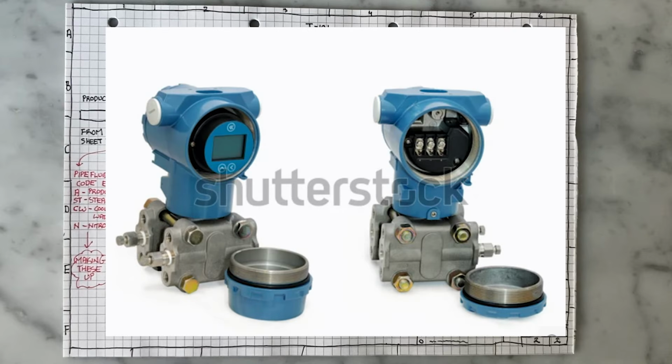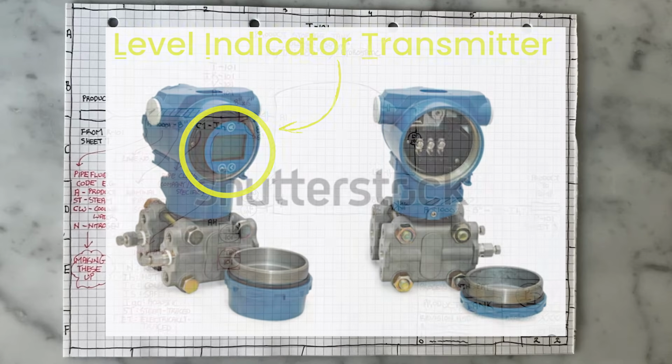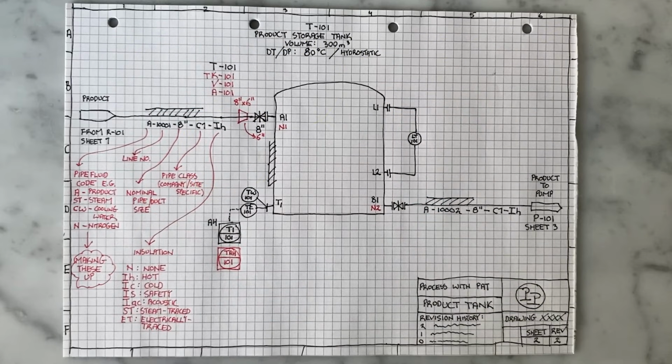Now, the picture I showed you of the level transmitter on the left, you can see that it actually has a digital display, meaning I could locally see what the reading was. If this was the instrument used, I would have used the label LIT, level indicator transmitter, because there is an indication. However, many DP cells don't have that indication and are simply a transmitter. In that case, we use LT without the indication.